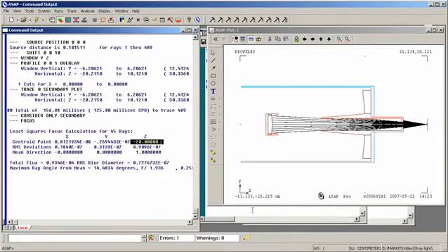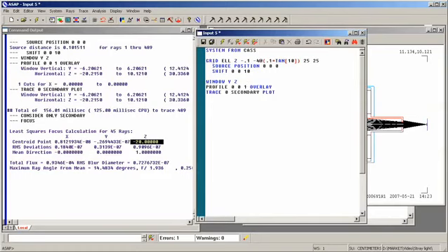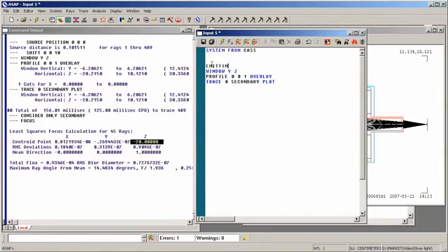We're going to use the same idea, but we're going to use an extended source, not a point source. Instead of our grid, we'll use an emitting rectangle. We'll again place it on the detector, actually just slightly off of it. The size is the same. That is to say, the detector dimensions are 0.15 by 0.15. Same thing. And we have to tell it how many rays to trace.